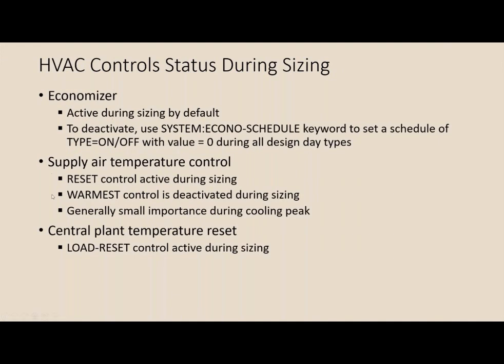So here's a couple of points about HVAC controls and what goes on with those during the sizing parts of the simulation. Outside air economizers are active during sizing by default. And in the work that I've done in the past, there have been some cases where the economizer has fouled up the sizing calculations.